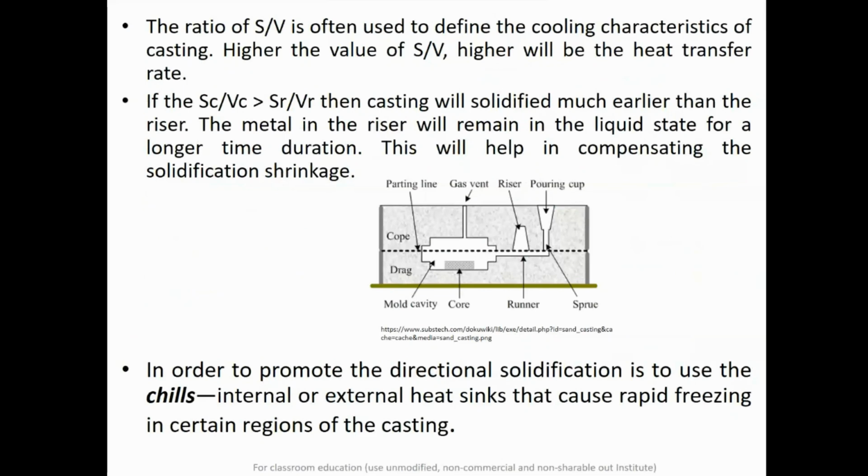So the ratio of surface area to volume is often used to define the cooling characteristic. And the higher this S by V value, the more heat will be transferred away from the casting zone. If the surface area to volume of the casting is greater than that of the riser, then the casting will solidify much earlier than the riser, and the metal in the riser will remain liquid for a longer time, which will help in compensating the solidification shrinkage. So these are some of the rules that we always remember while designing the riser.